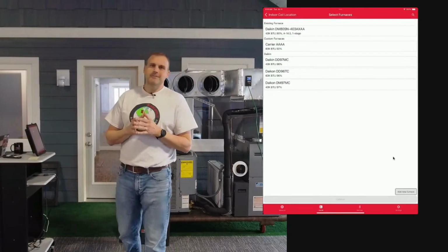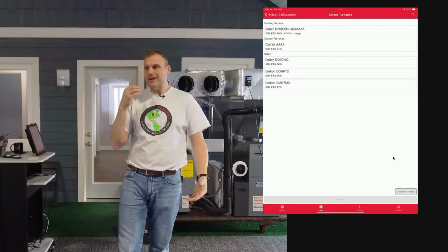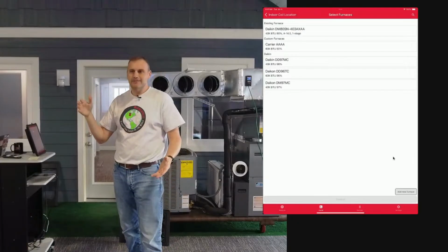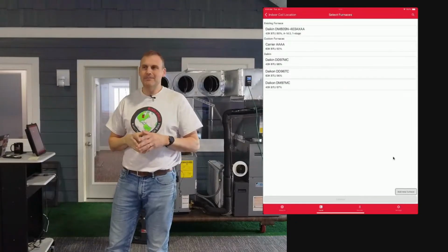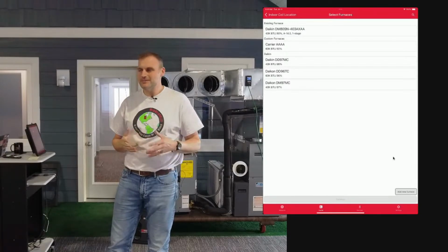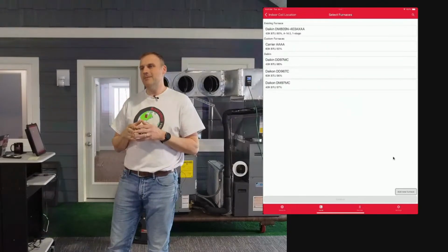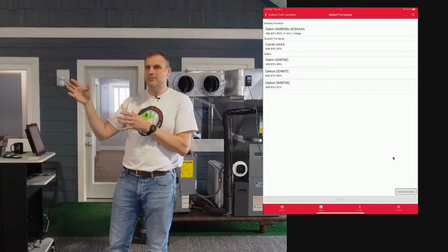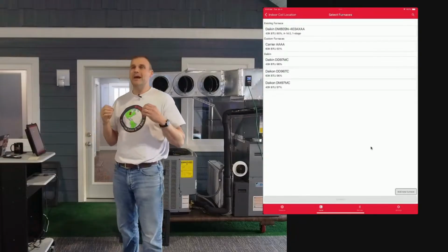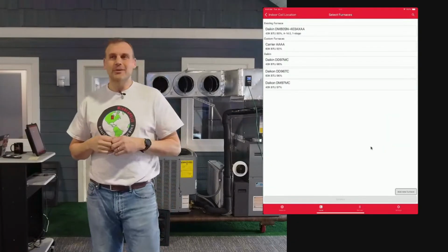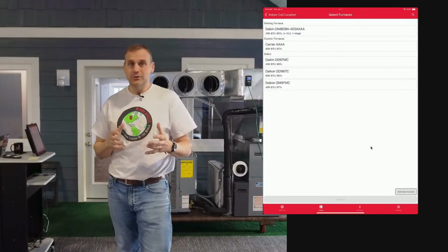Furnaces, you can't do that. Furnaces kind of have a wide variety of selection, and things are radically different because they have different temp rises, right? If you have a very high efficient furnace, it may have a very low temp rise. If you have an old school furnace, which you're not going to get something really old, but let's say you got an 80% furnace, you could have a very high temp rise that's available to you, which means you can move a lot less airflow to make it work in the duct system. All that being said, we had to go with a different strategy. So instead of design and find, now the strategy is choose and use.